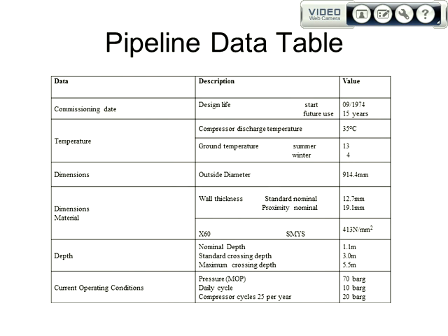Temperature. Basically, it's under gas use, the compressor discharge temperature, the maximum temperature of the pipeline, so this is 35 degrees C. Otherwise, it's going to see the ground temperature. Okay, so you need to consider that. That's important when you start looking at the CO2 phase diagram. The outside diameter is 914.4 millimeters. The wall thickness, the standard nominal wall, is 12.7.